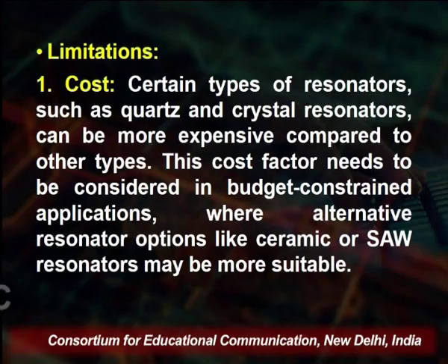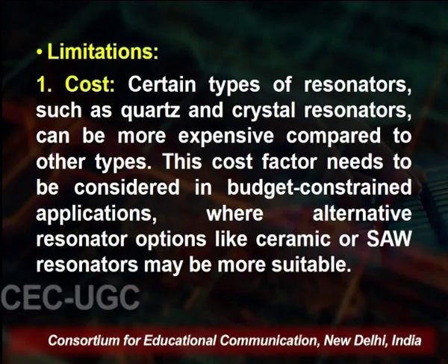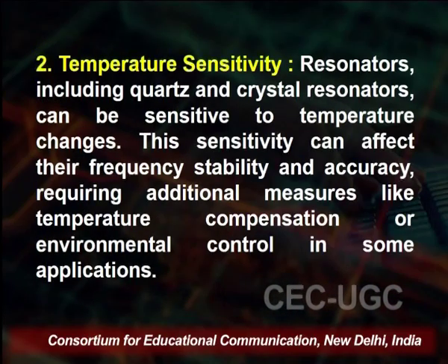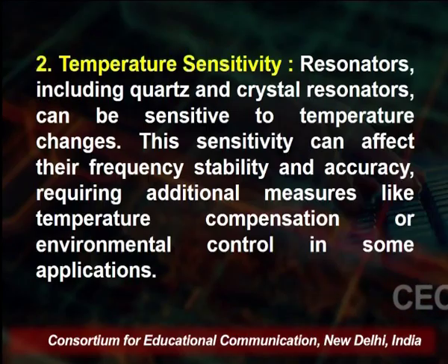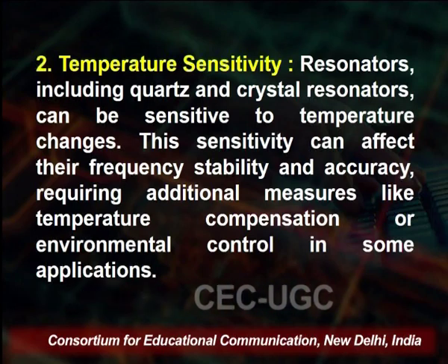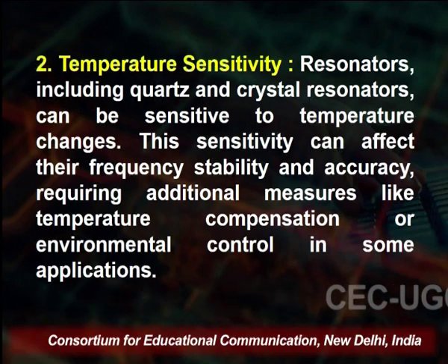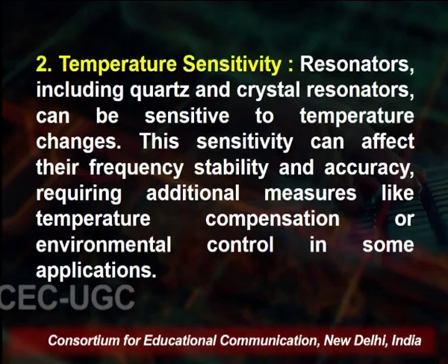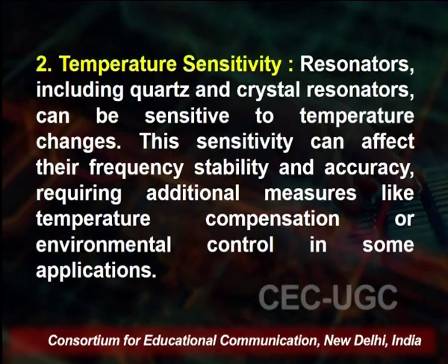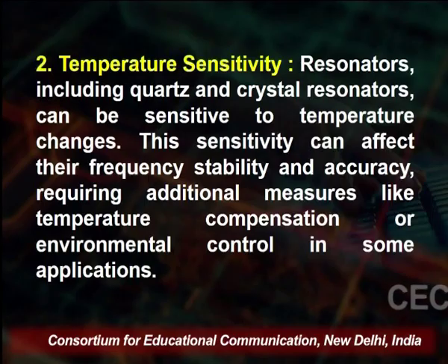Another type, the ceramic SAW resonator, may be suitable if we talk about cost. Temperature sensitivity: some resonators including quartz crystal resonators can be sensitive to temperature changes. This sensitivity can affect their frequency stability and accuracy, requiring additional measures like temperature compensation or environmental control in some applications.